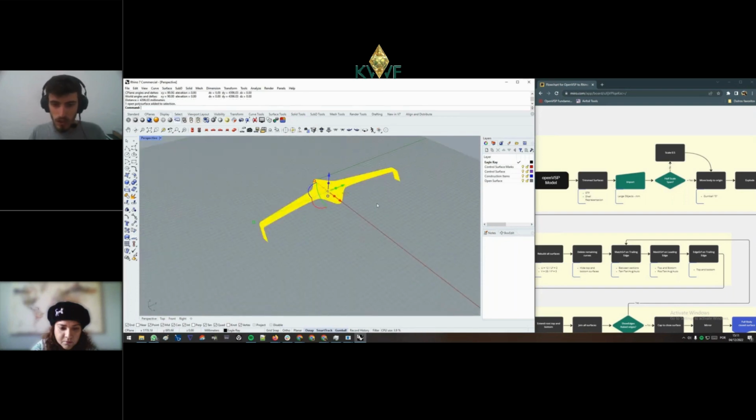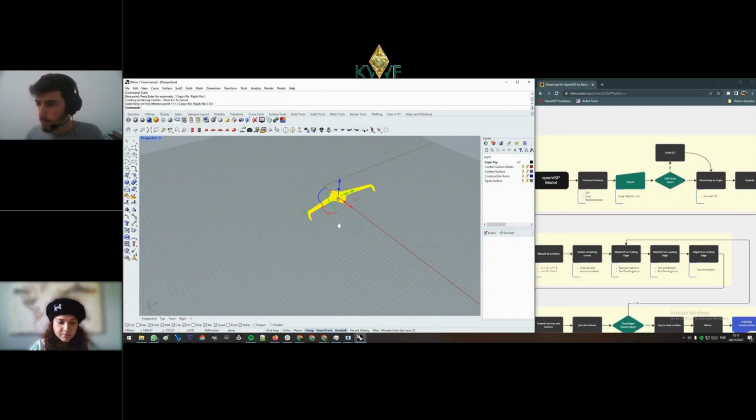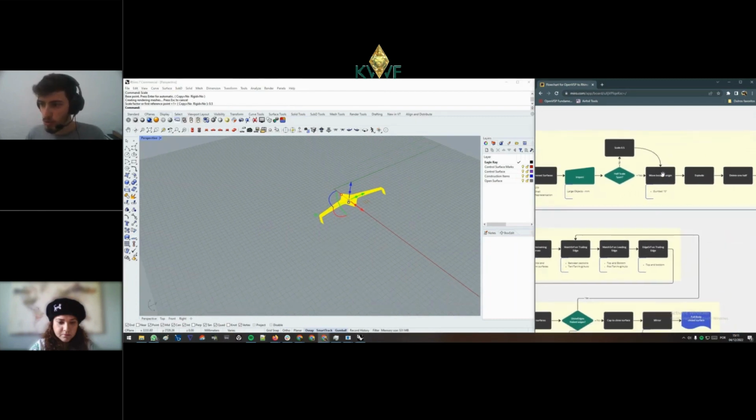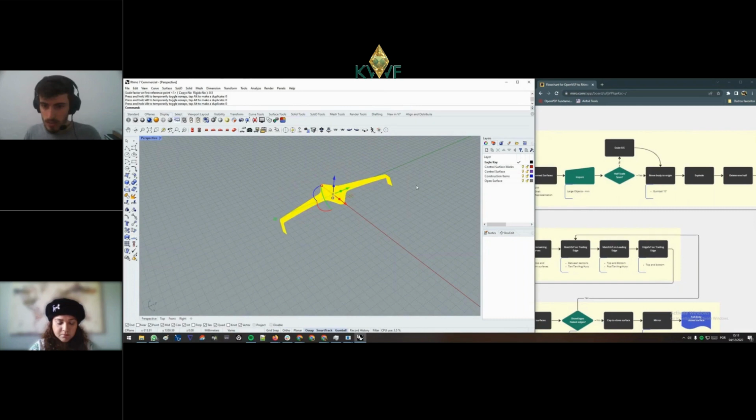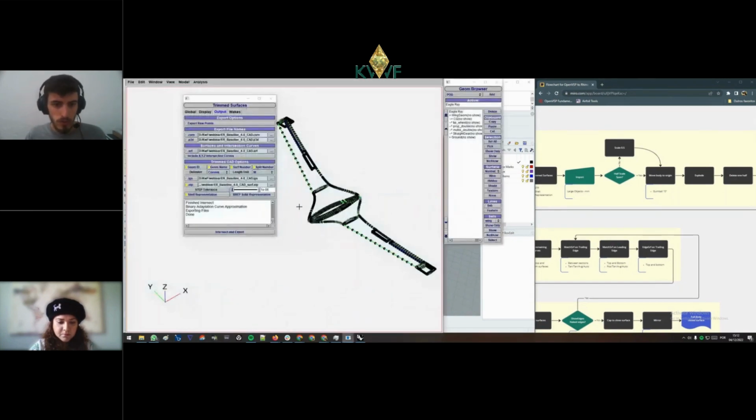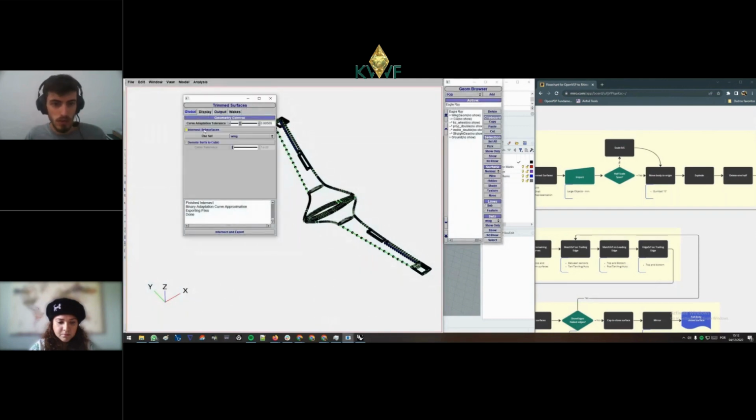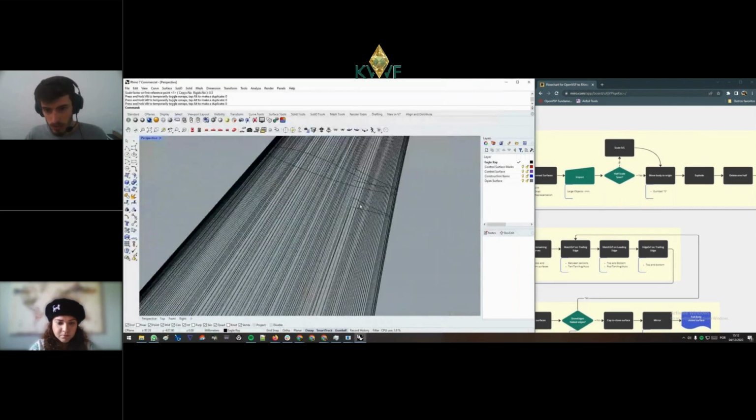So I'm just going to scale everything here with the automatic base point, which will be the volumetric center of the body, and I'll scale half. Now I will move the body to the origin just to make things easier later in the 3 axes. Since we exported from OpenVSP as trimmed surfaces with the subsurfaces intersected, we have the subsurfaces here.